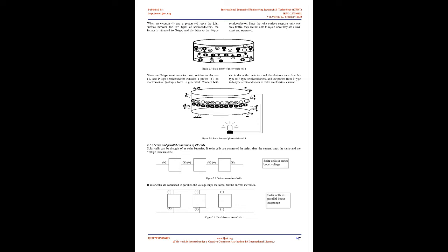Several grid-connected photovoltaic system topologies are used in existing installations. D. Picault, B. Raison, and S. Bacha [11] presented a paper that proposes evaluation criteria for comparing and choosing topologies compatible with the user's demands. After presenting an overview of current architectures used in grid-connected systems, five key points for comparison were discussed: topology upgradability, performance under shaded conditions, degraded mode operation, investment costs, and ancillary service participation. The proposed method can be adapted to the user's particular needs and expectations of the photovoltaic plant. These evaluation guidelines may assist grid-tied PV system users to choose the most convenient topology for their application by weighting the evaluation criteria.